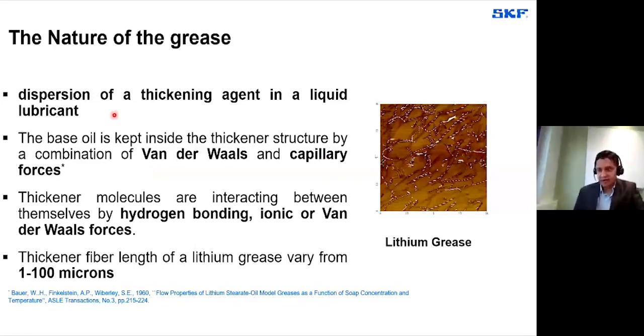One is the thickening agent, which acts as the dispersion phase. Another one is the liquid lubricant, which acts as the dispersion medium. So if I want to define a grease, it's a solid to semi-solid product, or a dispersion of a thickening agent in a liquid lubricant. Then how exactly is this base oil kept inside the thickener structure? It's mainly by the combination of van der Waals forces and capillary forces.